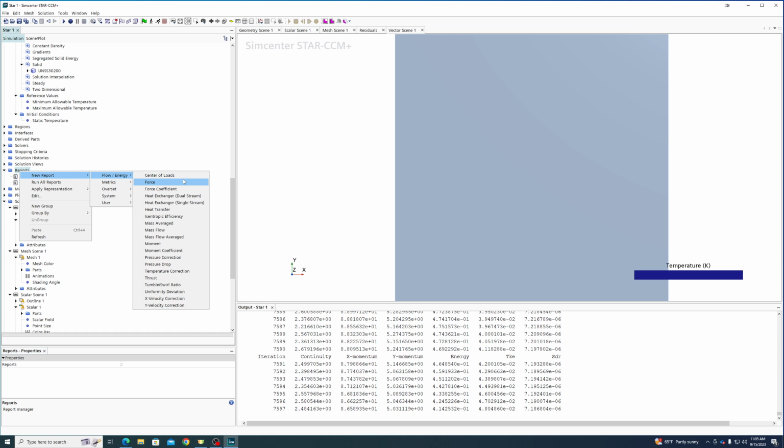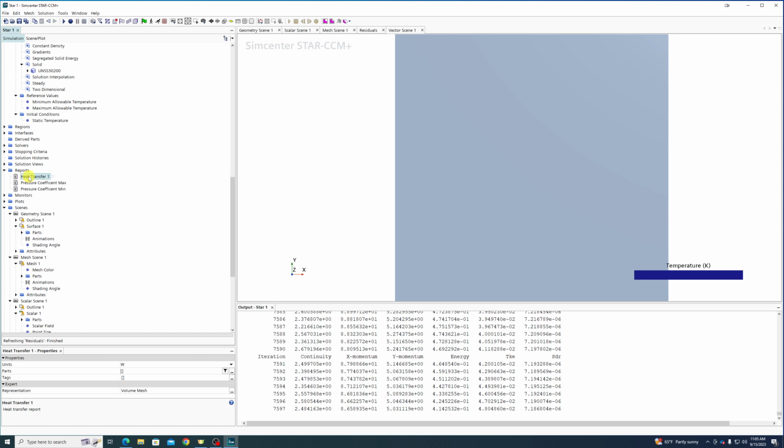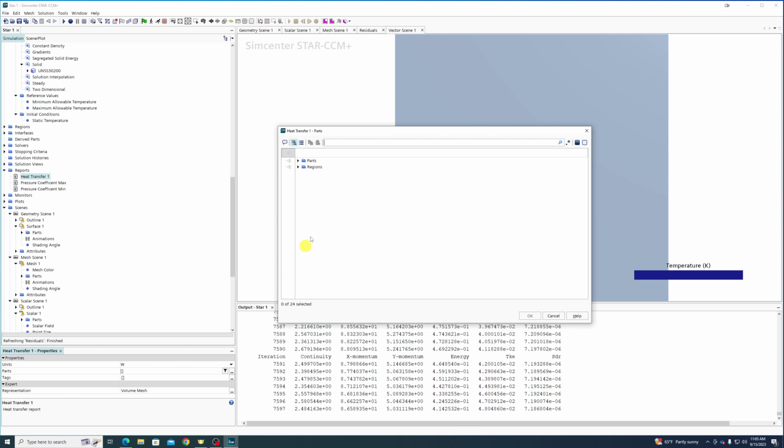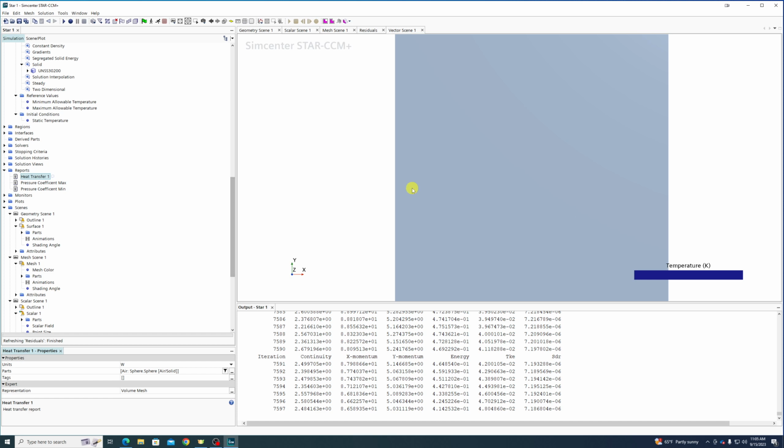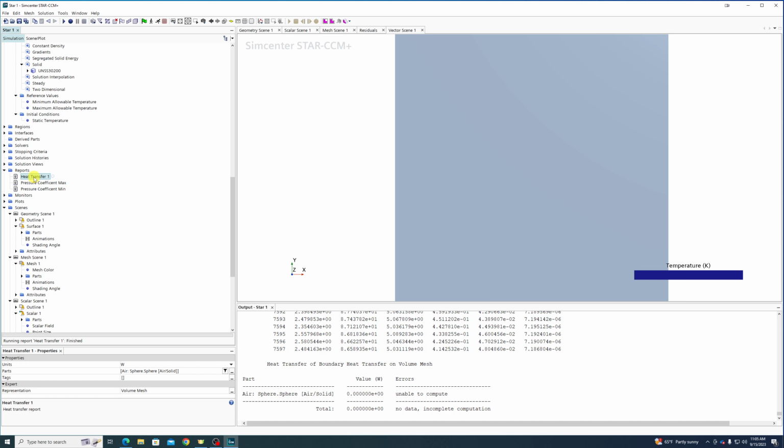Most of these values we're looking for on the air side, realistically. We want to know also how much heat transfer is moving through that surface. So you can select either side of the interface. The important thing is this adheres to the vector math for heat and fluid flow. Heat moving into the domain is negative. Should be. We have no data at the moment. But heat flowing into the domain, I'm very certain is negative. Heat flowing out will be positive.